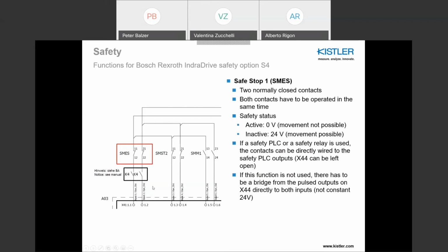If you're using a safety PLC, you can directly connect the outputs here from the safety zone box. And important is, if you're not using the IndraDrive function, you simply need to make a bridge. Please do not leave it unwired, because otherwise this function will always be active.